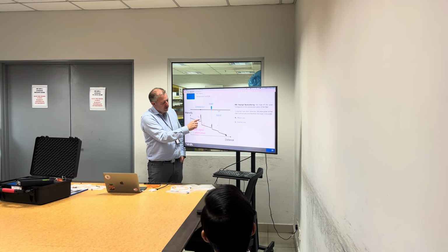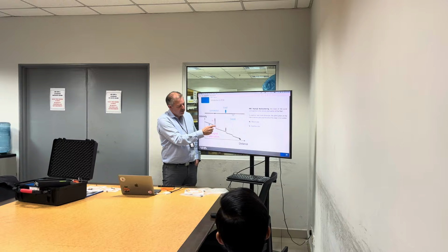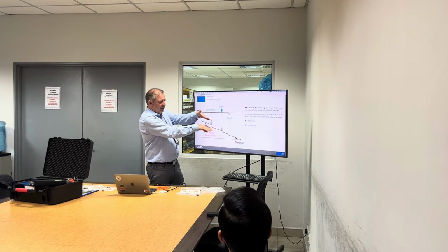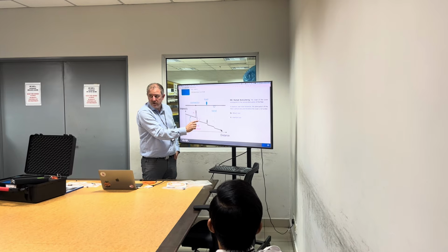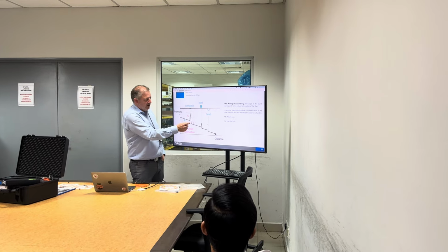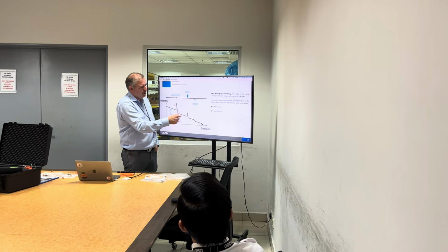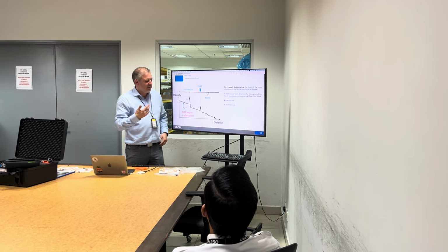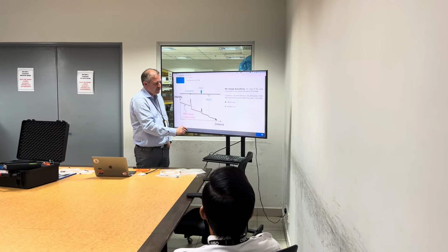And then after that, usually you have a fall, so you have lost some light because some has been reflected. The difference that you have here between this and this, so you take the two parallels of the slope, and the gap here, the step, is called insertion loss. So this is what we are going to look at, and that gives you the power you lost at this location. So this is another example of a fault. For example, a fault would be if you compress the fiber. I don't think you're going to have many of these cases, but in case, it will look like this: small reflection and again a small insertion loss.